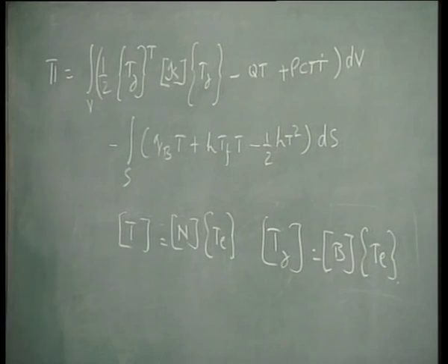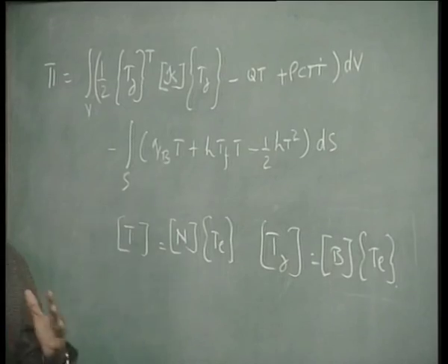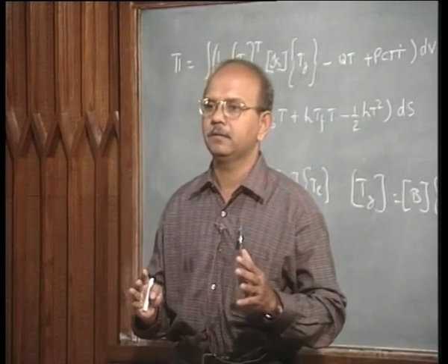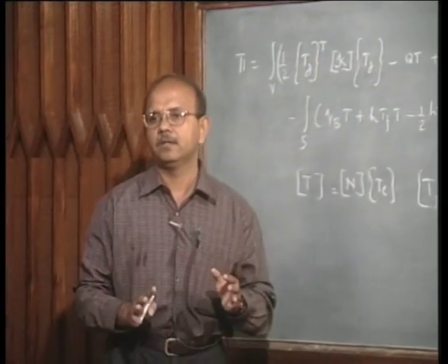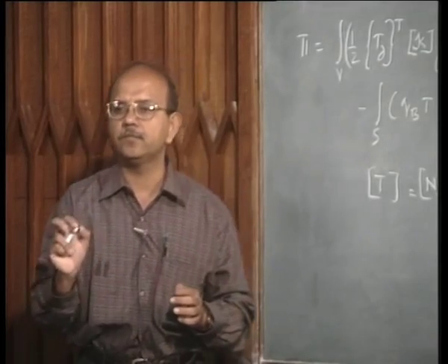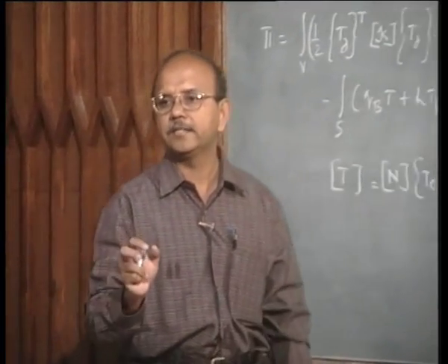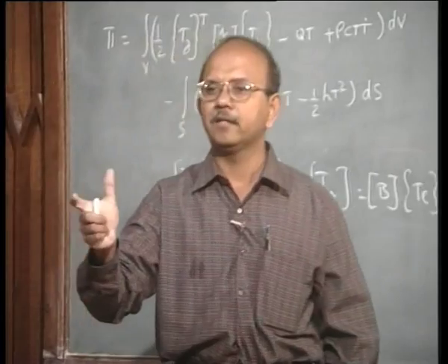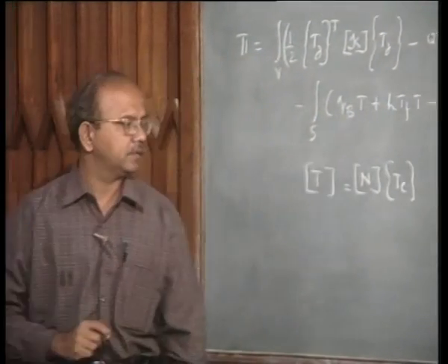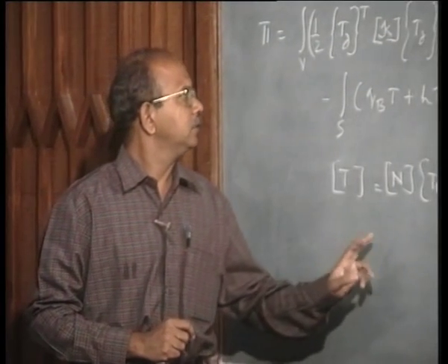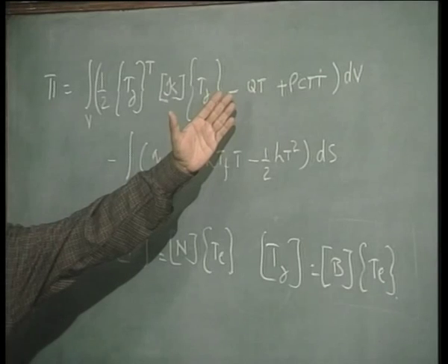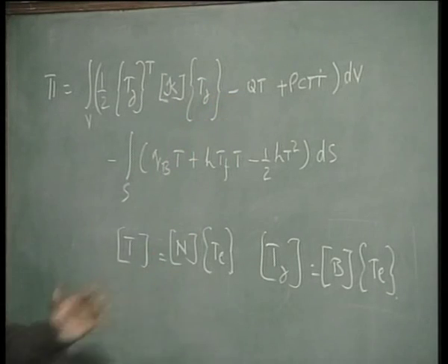For an isotropic material where K is the same in all directions, what does it become? K 1 0 0 1. So, K in the diagonal, this is a 2 by 2 matrix. So, kappa takes the diagonal terms and the off-diagonal terms go to 0. This is for an isotropic material. Is that clear? So, now how do you write this equation with the help of this?